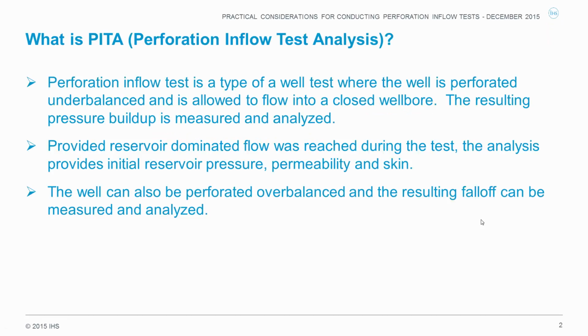So what is PITA? PITA is an acronym that stands for Perforation Inflow Test Analysis. The perforation inflow test is a type of well test where the well is perforated underbalanced and is allowed to flow into a closed wellbore. There is no production to surface, there is no metering of rates. The resulting pressure buildup is measured and analyzed.